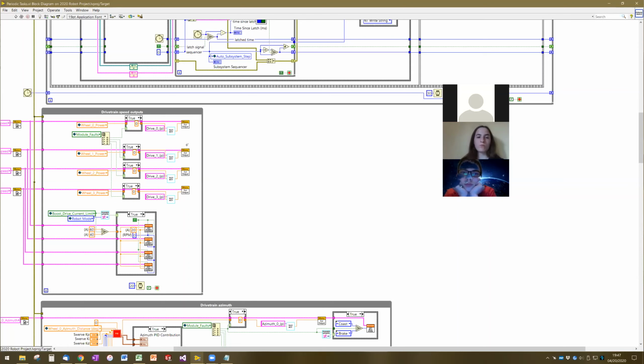The advantage of this is not really important for a non-Swerve robot. For a Swerve robot, that is a bit important because you are merging instructions about how the robot should translate with how the robot should rotate, and that's what we're going to talk about. And the merging of that information relies on power being directly related to wheel speed.